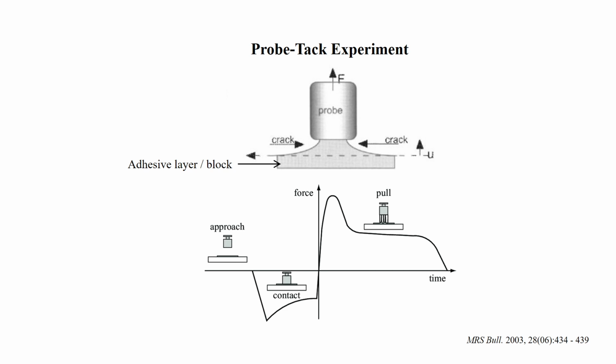I would like to show you here a typical curve that happens. We have this particular probe and we first bring it in contact. When it is brought in contact, as we press it, the load decreases over here. So, this is basically the compressive load, so it is negative over here, and now we try to pull it off. You will see that there is a pull-off force that is required to separate it. When you try to pull it, it remains in contact for some time, and then a crack propagates, and this particular probe separates out over here. So, we want to see this whole history of loading and unloading.